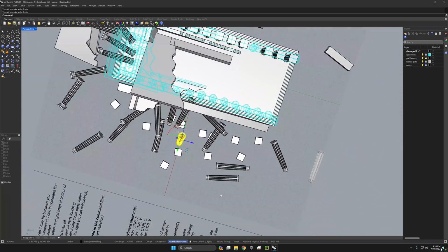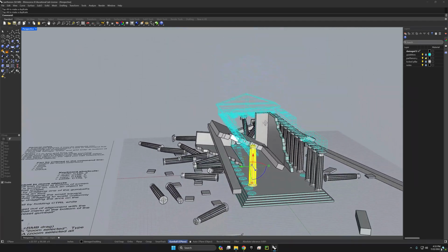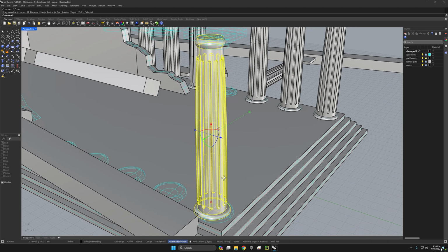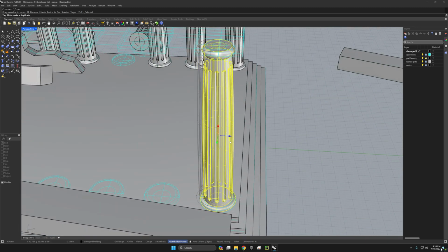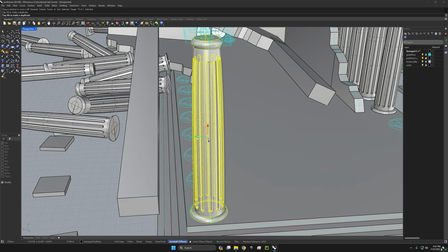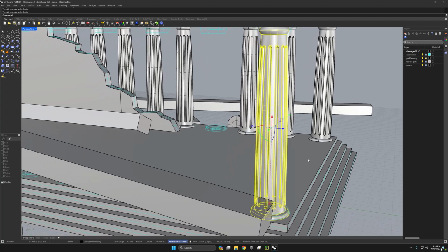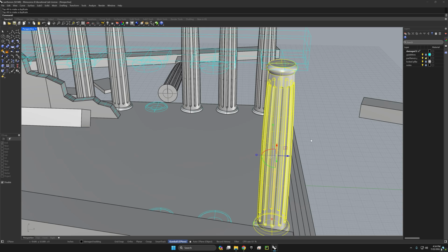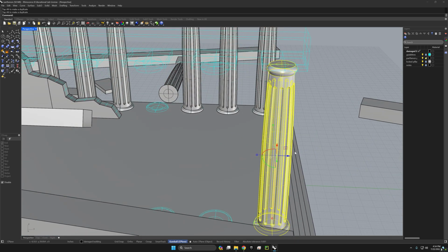Now we can go so that we're in perspective looking down on the form and move it down in space some. Now I'll type in ZS to zoom selected. Scoot it over a bit. There are more precise ways of moving things around. I'll show you some methods toward the end of the tutorial. But for now, it would be good to go ahead and pause the video and move some items into place so that you get familiar with how the gumball works.